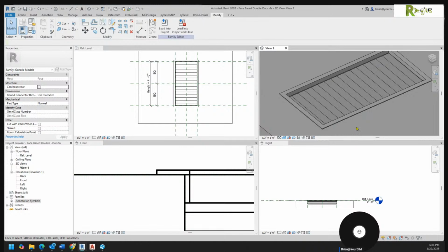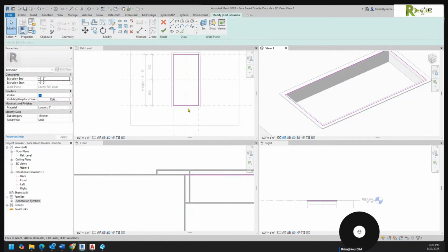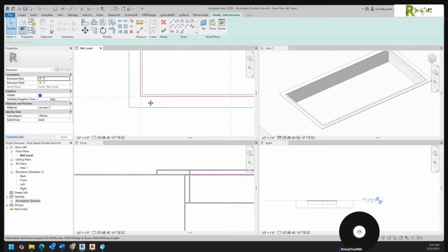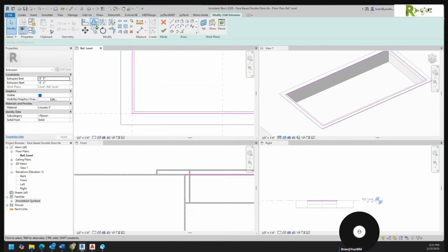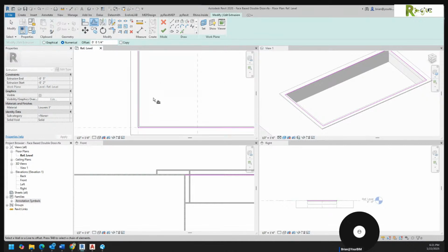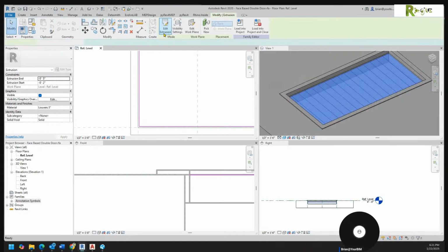All right, another type. Now, really, that means this guy, if I came in here, really needs to be set off that 1/4 inch. How do I do that? I go to offset. I say a 1/4 inch here. This is always a pain to type. Don't move your cursor while you're doing that. And then I go to copy, come back down here, click once in white space. And now I can actually hover over it and hit tab, and it'll go all the way around that circle and move that guy in.